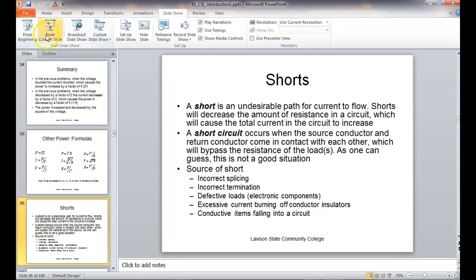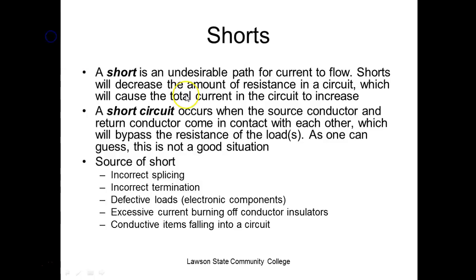Not going to be a short, because a short would blow a fuse, and my lights would never come back on. So that's the problem we have. A short doesn't mean we lose current. A short is a what? An undesirable path. So we still have current flow. It's just that I've lost control of the path. Normally we like to control the path that the current flows. With a short, we've lost control of that.